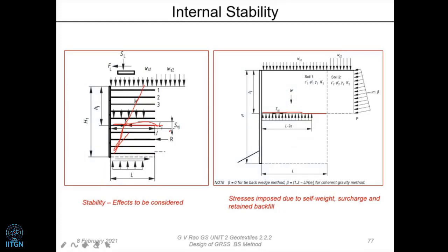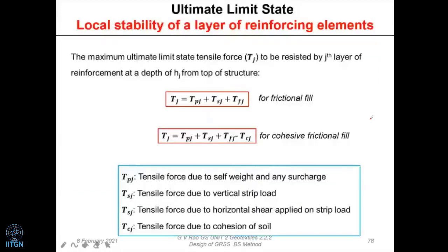And what else is going to be there? The entire geotextile is going to be used basically. It's not in pieces. Okay, and then this is the area, this is the command area you can say, and that earth pressure we are going to consider for the safety of this entire thing. So we find out whether the friction is sufficient or not by initially assuming this length from the stability. If it's not sufficient, we will increase the length. Once you do that, the friction is enough to transfer it as a tension. So the tension value is going to be exactly the same as the earth pressure. Nothing more than that. So that is what we try to do.